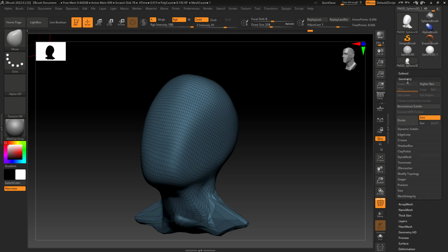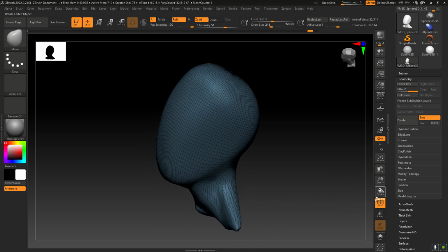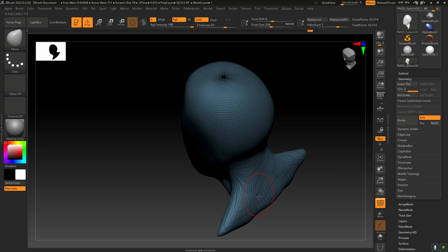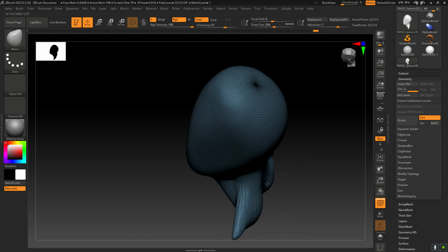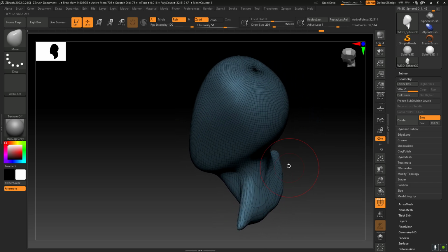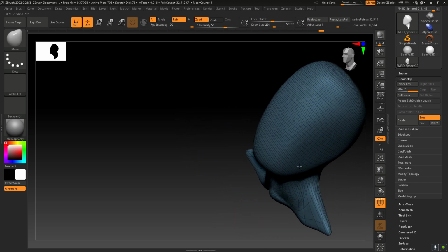In subdivision levels, what happens is, if I click 1, Control D, one more level of mesh will be increased. Here it is showing division 2. In division 2 the polys are not spoiling anything. So it is making it a little more smoother for you to edit the object, so that we are going to edit the object.